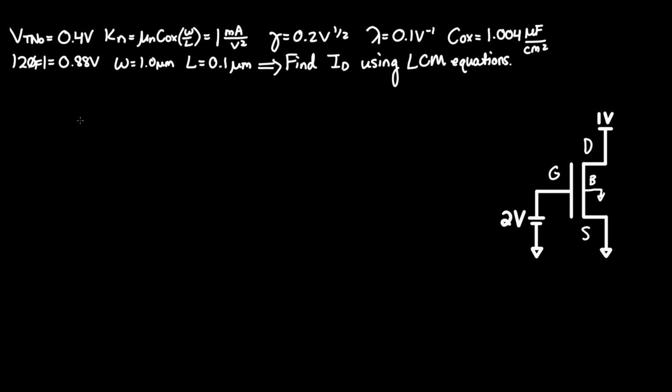To analyze this MOSFET, we have to first see whether or not it is on or off. We can tell given VGS being greater or less than the threshold voltage VTN. So starting off, we need to see that VG of VGS is this voltage at this node of the gate here, connected to 2 volts.